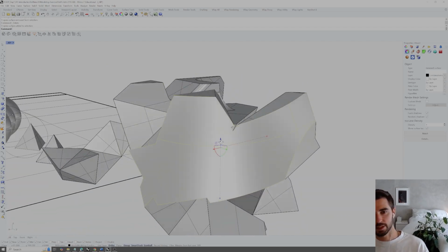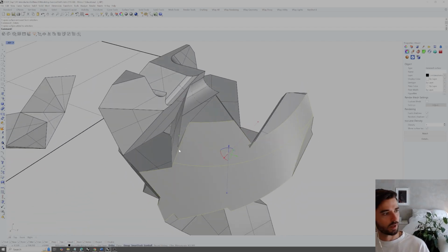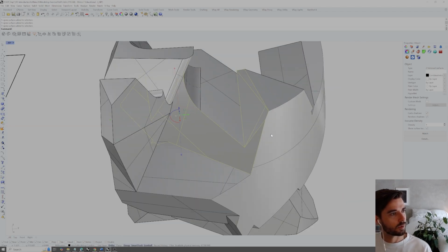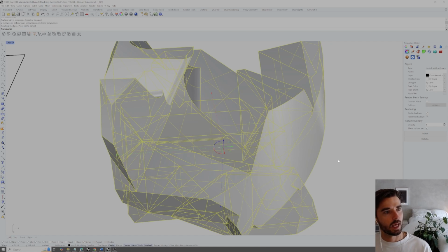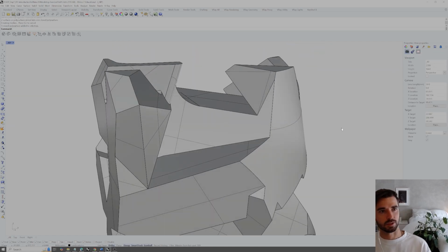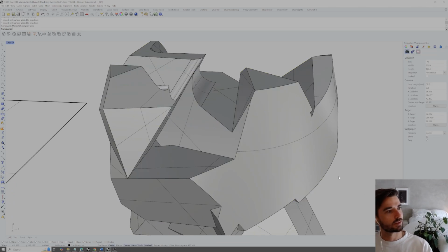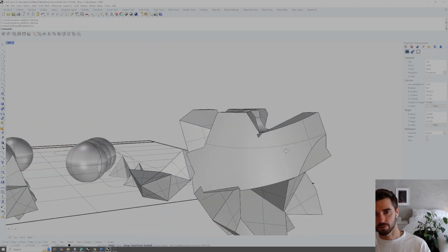And now we have a nice clean geometry there at the edge with none of those little pockets at this corner. And now each one of these should be able to neatly rejoin and join with the original poly surface, which is now nice and closed. And just to be safe, we can merge all coplanar faces to get a nice clean version of this poly surface.